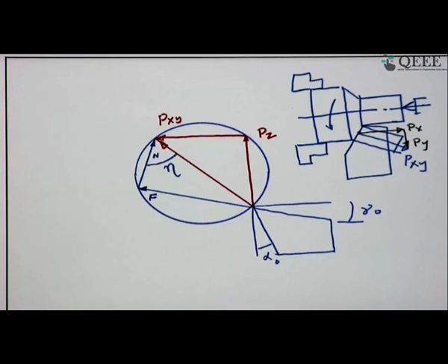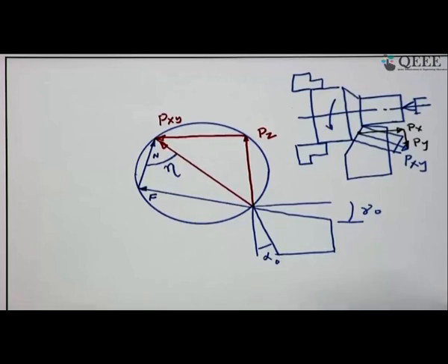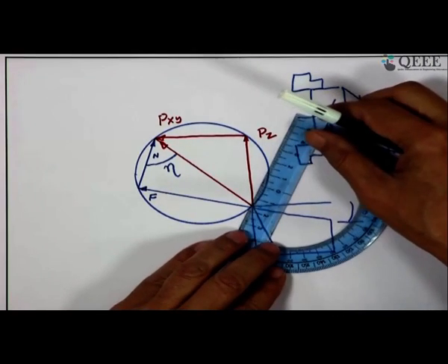What remains to be done in this diagram, and after drawing these lines it will be completed, we have to identify the direction of the shear plane. So, from the lesson we covered yesterday, we know how to determine the shear plane angle from the chip thickness and rake. There are standard geometrical relationships. So, from that we get to know how to get the shear plane. So, this shear plane orientation I also have to show here.